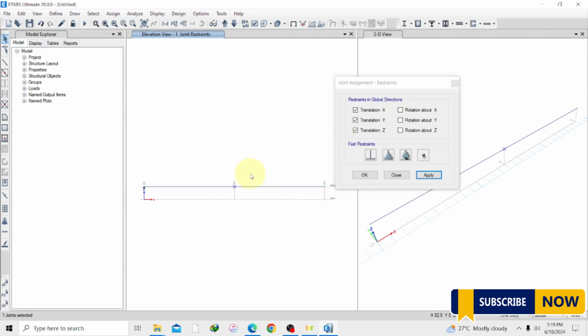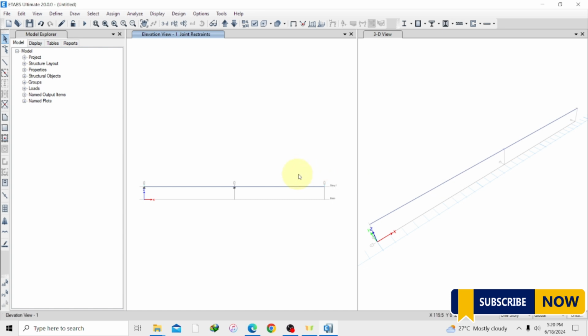It's normal if your loads are not there. They are there, but they are not showing, since I'm considering supports now here. And I'm going to apply my roller supports. This is the roller supports, then apply to that point, then OK. So now everything is intact and I'm done with everything.